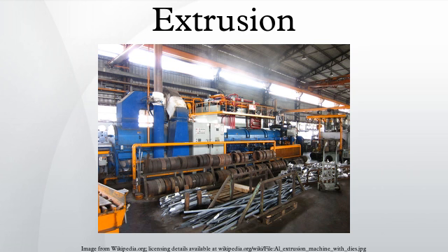In the extrusion process, raw materials are first ground to the correct particle size. The dry mix is passed through a preconditioner, in which other ingredients may be added, and steam is injected to start the cooking process. The preconditioned mix is then passed through an extruder, where it is forced through a die and cut to the desired length.